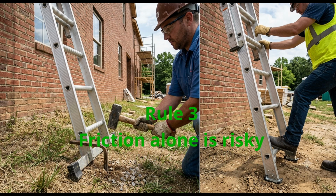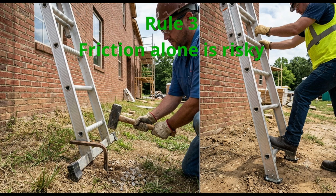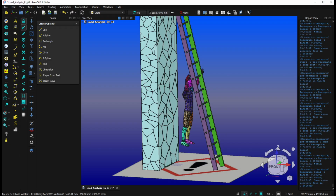Number 3, ensure the base is fixed. Relying on friction alone is incredibly risky. Double check it if you have to go up a ladder unsecured. So that might be going around to the other side or the underside of the ladder and hanging off a point as high as you can get and assessing its stability before attempting to go up.